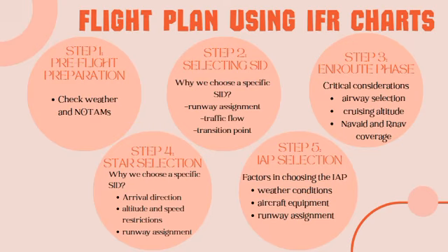Step 2 is selecting the appropriate SID. The SID connects the departure runway to the en route airways in a standardized and predictable manner. Why do we choose a specific standard instrument departure? Because of the runway assignment, the SID must align with the departure runway.